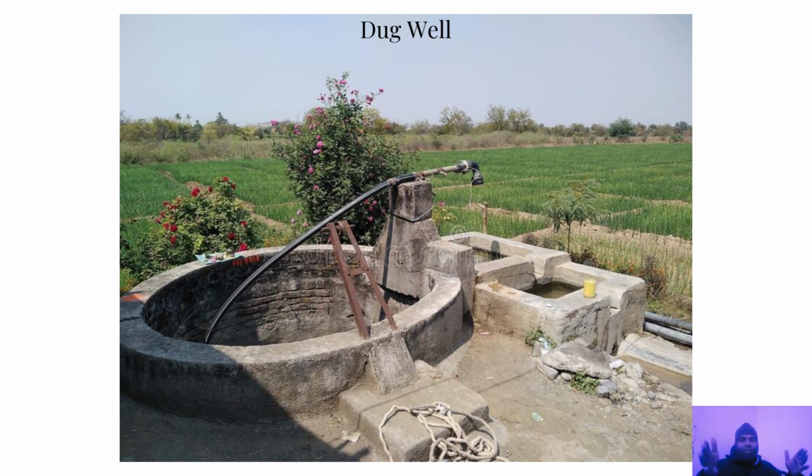Now, you also have dug wells in a large part of the country, which are different from bore wells because they are relatively large in diameter. However, today, in the modern day, very few places use dug wells. They were mostly used at a time when the drawing of water was done by hand and not by pumps. Wherever there are dug wells, you can put a submersible pump in and you can pump out the water.